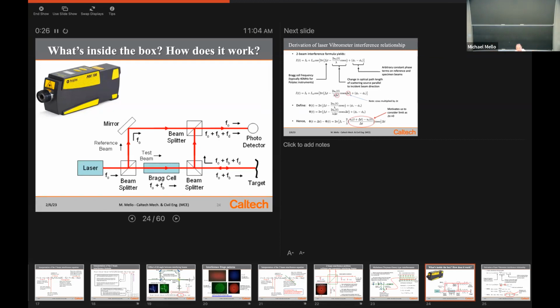There's a little bit missing. What's missing is the output of that photodetector. The output of that photodetector gives the time averaged response. And what we saw from the derivation is that the time averaged interference signal that you get doesn't have the electromagnetic frequency of light in it any longer.